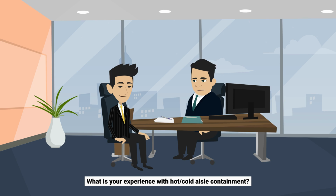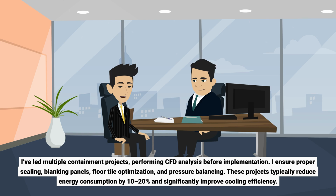What is your experience with hot/cold aisle containment? I've led multiple containment projects, performing CFD analysis before implementation. I ensure proper sealing, blanking panels, floor tile optimization, and pressure balancing. These projects typically reduce energy consumption by 10 to 20% and significantly improve cooling efficiency.